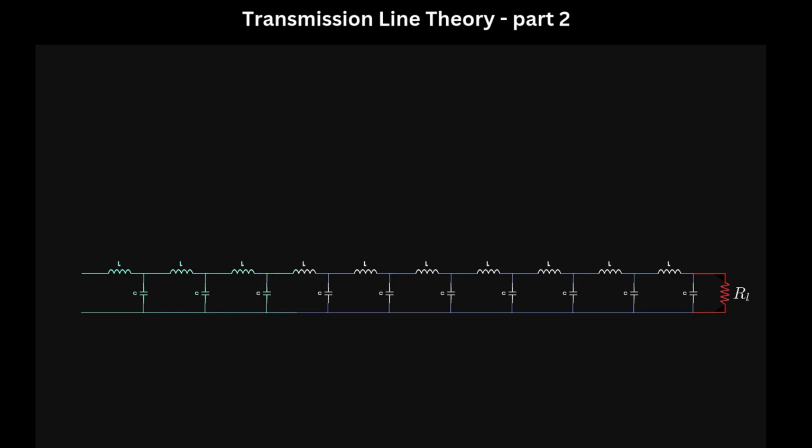The voltage at the input of the line is 200 millivolts from voltage division, let's call it V1, and it injects constant current during that trip, irrespective of the current of termination. When the signal finally reaches the end of the transmission line, the voltage at the endpoint becomes V2, depending on the value of the termination resistance, so that the ratio of the voltage over the current equals the load resistance, and the current drawn by the load resistance settles at V2 over RL.